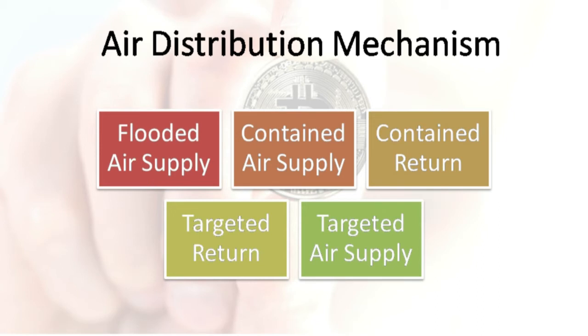As for the last two, targeted supply and targeted return architecture, you will still utilize either the overhead ductwork or the raised floor to direct either the cold or hot air. However, in this case, it would not be directed into or out of an enclosed environment.